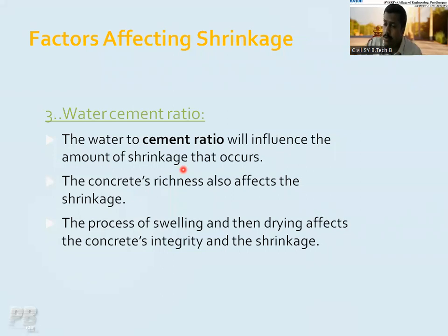So absorption of water into the concrete body and evaporation of water from the concrete body, due to this process, again it will affect the shrinkage. Alternate swelling and drying will affect the concrete integrity and the performance of your concrete body, and then it may lead to shrinkage. So this is all about the factors which are affecting the shrinkage.